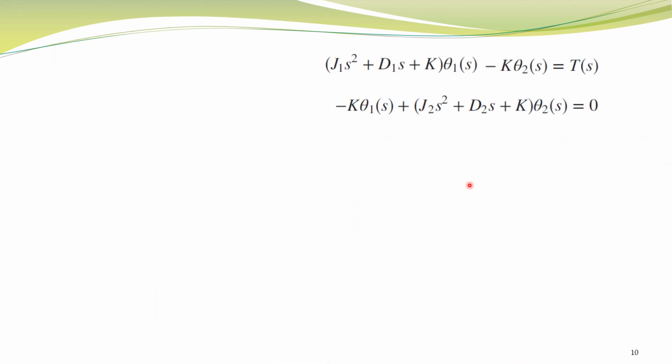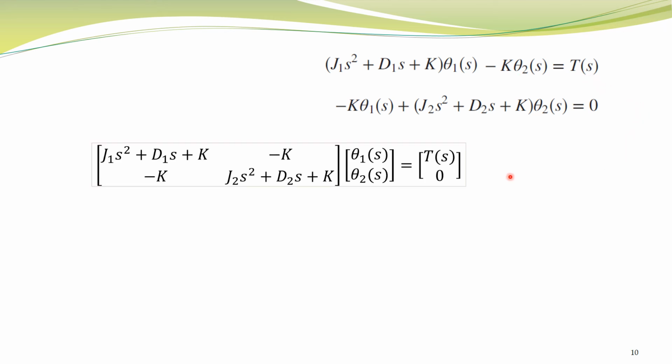Once we have these equations describing the mathematical model, we can also obtain the transfer function. Let's assume that we are interested in obtaining a transfer function between angular displacement theta 2 and the applied torque T(s). We can proceed in different ways. For example, we can apply Cramer's rule.